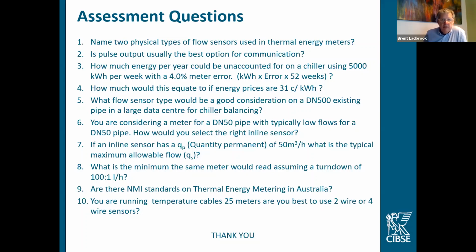Are there NMI standards on thermal energy metering in Australia? If anyone answers yes, my mission has been unsuccessful, so it's not possible. And the last question, you are running temperature cables 25 metres. Are you best to use 2 or 4 wire sensors? You may recall before, anything over 10 metres, definitely go for a 4 wire sensor. So if you have any questions, hang around. We could even turn microphones on if anyone wanted to hang around, or email me, or do whichever you like.